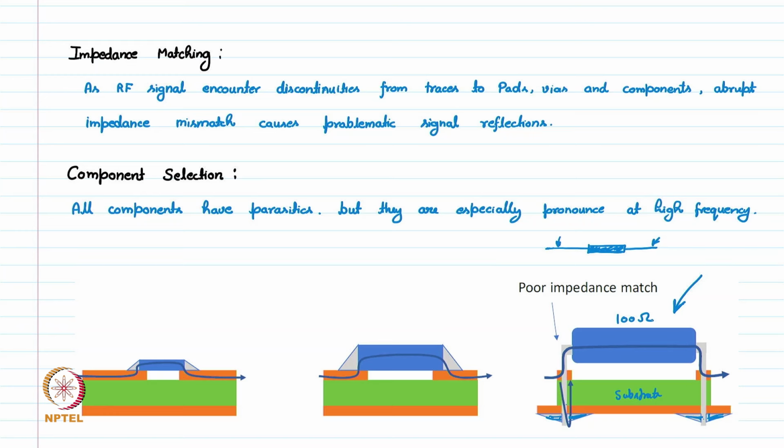Now the problem in this case is, at lower frequency this will work fine, but at higher frequencies we have so much of parasitic capacitance as well as inductance. So whenever we have a wire, these are extra wires coming out of this resistance. Resistance is only this much. This is the overall resistance. These are just connecting wires.